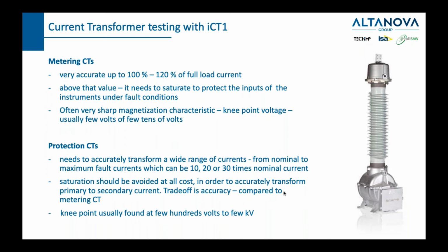And because they need to saturate after fault, in fault conditions, they often have a very sharp magnetization characteristic. And the knee point voltage is usually few volts to few tens of volts, depending on the application.